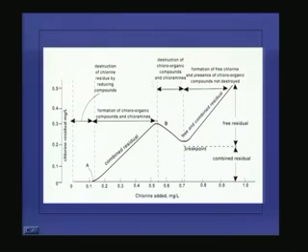If we add some more chlorine, at that time this trichloramine will dissociate, nitrogen gas will go out, and chlorine will come. So your combined residual chlorine will come down because NCl3 is getting destroyed from the system. So this is the break point, that means all the chloramines and chloroorganic compounds are getting destroyed from the system.